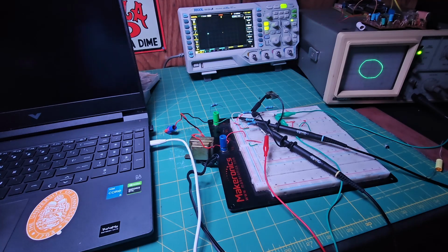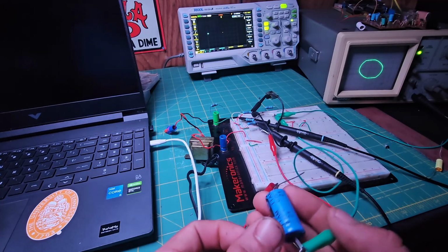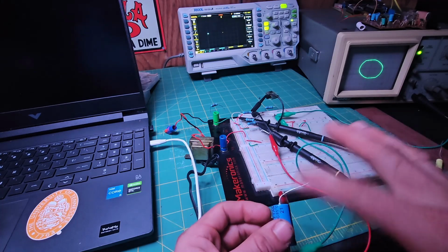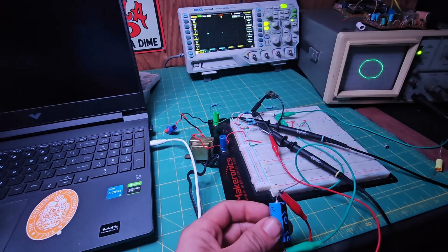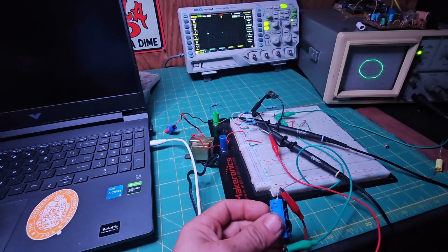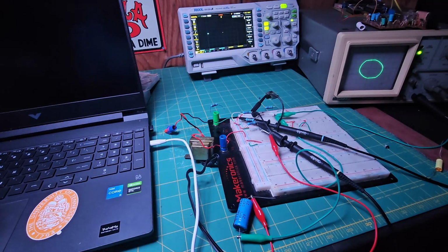Alright, so here's what's happening with this capacitor. So the impedance that this presents to the alternating current that's being given to it, if you were to measure this, there's about 9 volts of AC across this. That's why I have this little step-down transformer right there. But what happens is a capacitor does not impede the flow of current linearly. There are times where it flows more current and times where it flows less current.